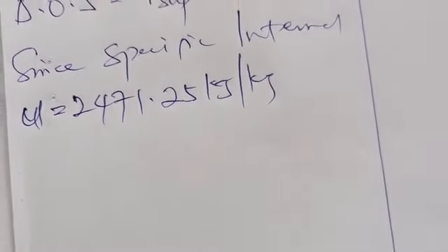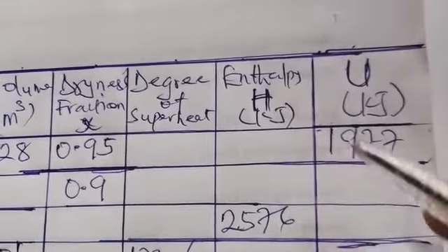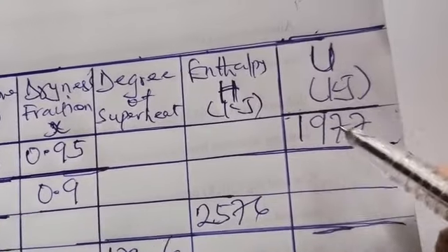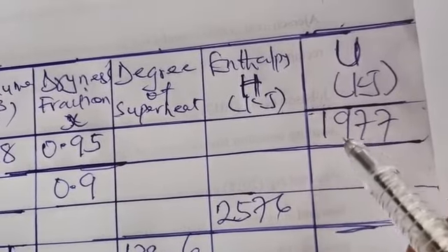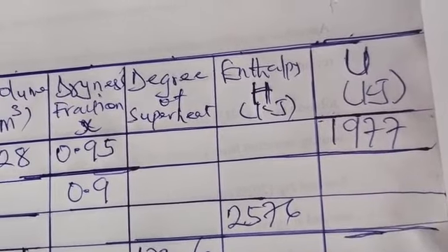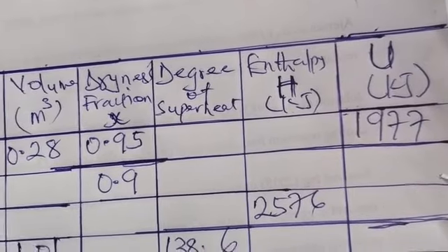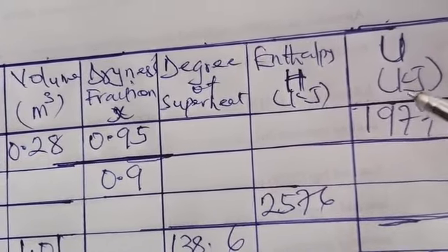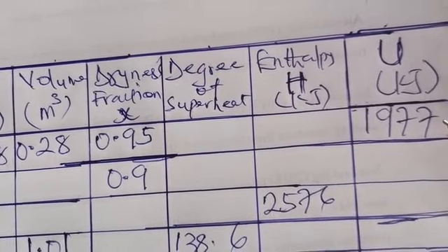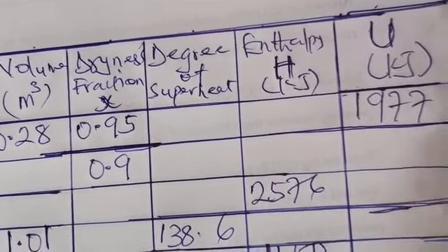The reason we're using that is simply because from the beginning of the question, that was the only thing given to us in the table. So we converted it to a specific property, and we have to check the temperature corresponding to this property from the superheated steam table. That's the temperature we use to subtract the saturation temperature.